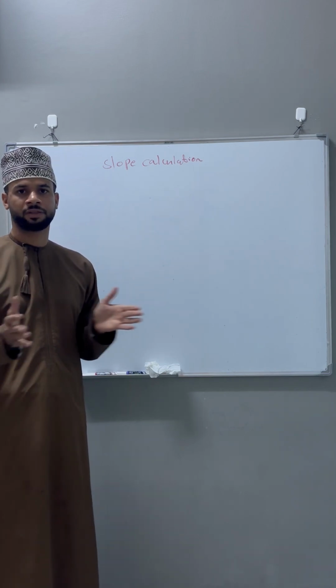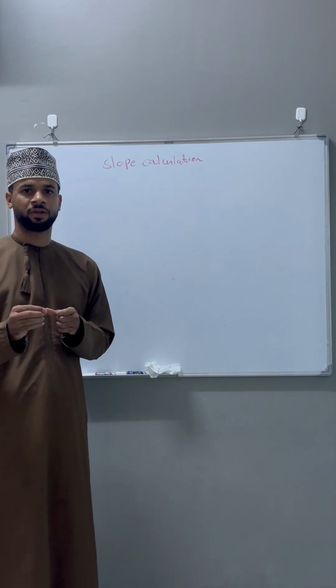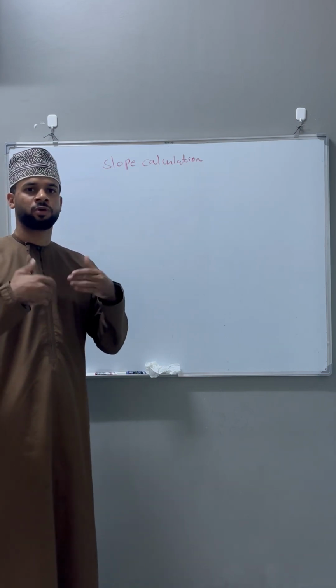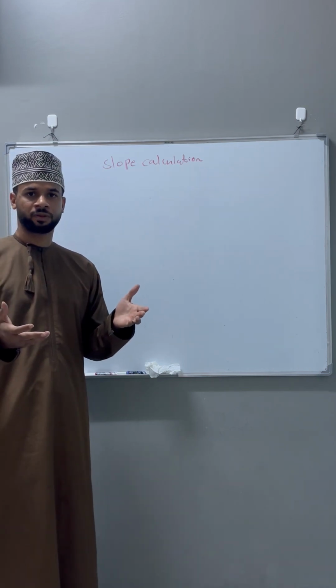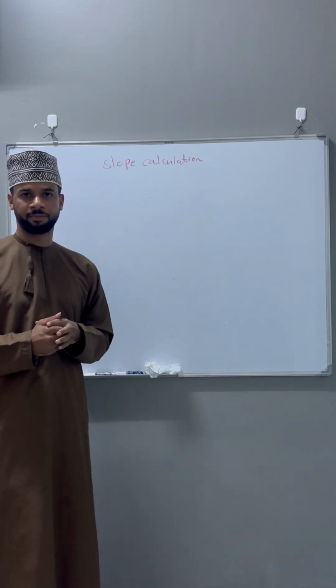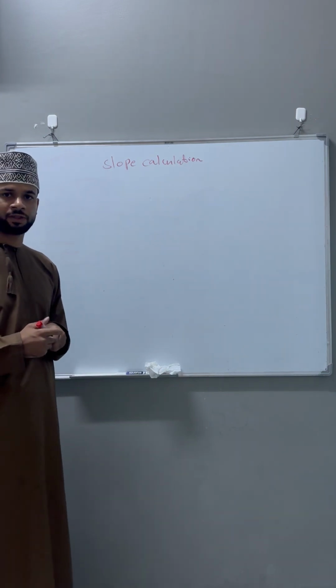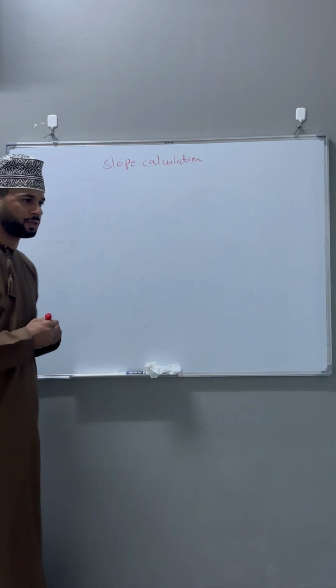And all these cases are not a real fault. It is not a real fault. Okay? So we don't want this transformer differential relay to trip. So that's why we need to create the slope in the transformer differential relay. Okay? So now how to draw the slope in a transformer differential relay.